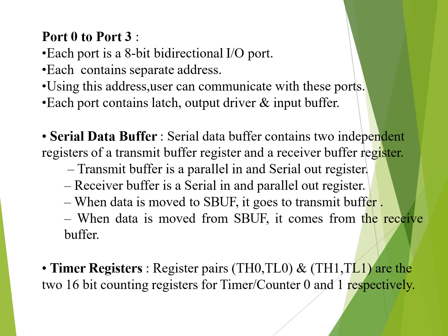So 8051 is having 4 ports starting from port 0 to port 3. All the 4 ports are 8-bit, and all these 4 ports are bidirectional input-output ports. All the ports are having separate addresses to address them. So out of all the 4 ports, only port 1 is the port which is not having any alternate function. The remaining 3 ports are associated with alternate functions.